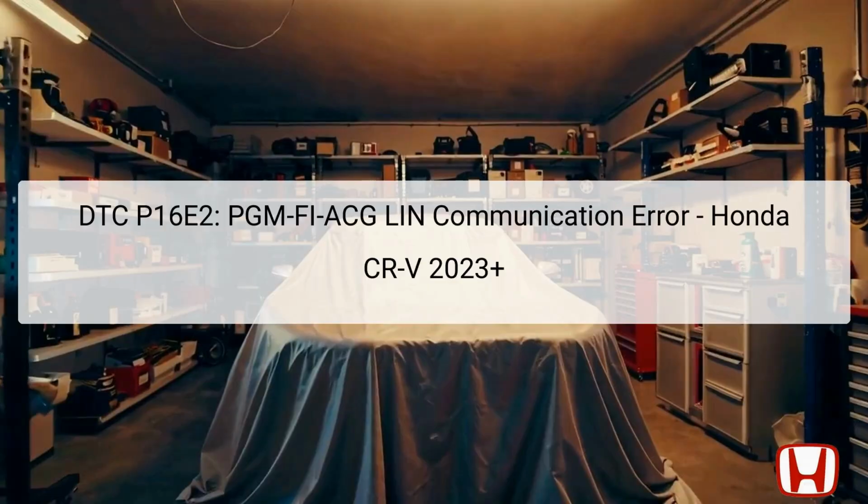The Diagnostic Trouble Code DTC P16E2 indicates a communication error with the LIN, Local Interconnect Network, related to the Alternator Communication Group, ACG. Specifically, this code is triggered when the Powertrain Control Module, PCM, fails to receive precise signals from the alternator via the LIN connection, leading the system to log an error.